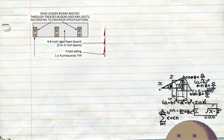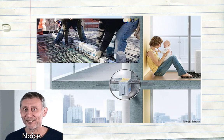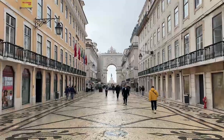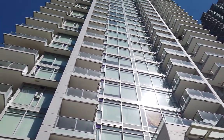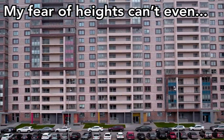Now, here is the big enemy: balconies. Everyone loves them, unless you are designing a passive house building. They are the number one reason for thermal bridging in your building. Maintaining insulation through balconies is tough, but doable. Prefab balcony connectors or structural thermal breaks are lifesavers, especially in high rises. It might be difficult, but balconies are a big selling point, and there is no developer who will accept not building them. So, we need to learn how to solve this.